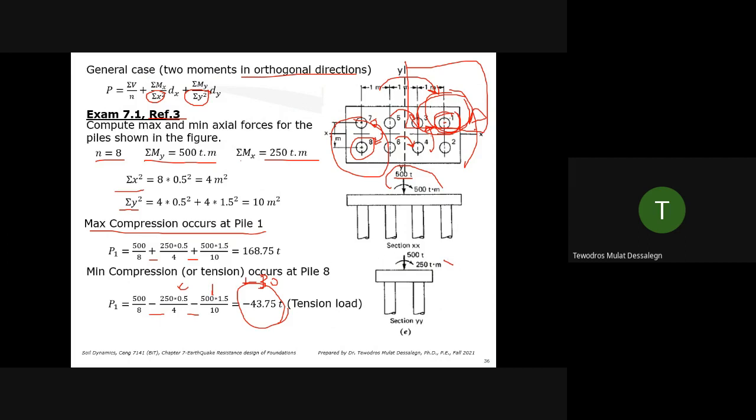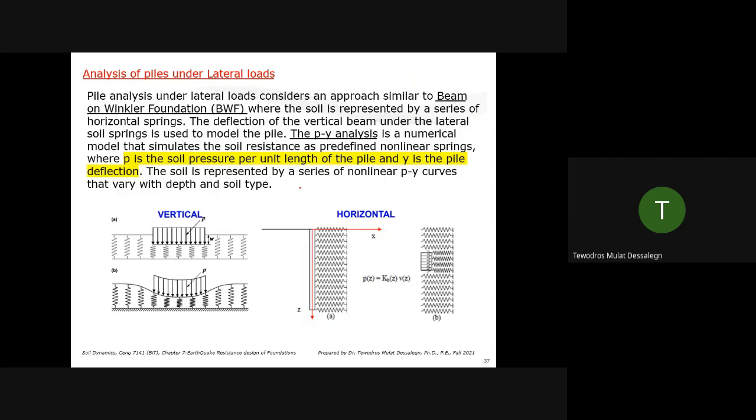Software can also do response spectrum analysis, but it will analyze the entire structure at any point, rather than considering a single degree of freedom system, which is much better. You'll have global modes, local modes, they will all be considered. But for hand calculation, usually the entire structure, we're assuming it to be a single degree of freedom system. Is that clear? You'll go through it more. You'll have the material, and I'll give you the slides, and you'll go through the numbers and the exercise.